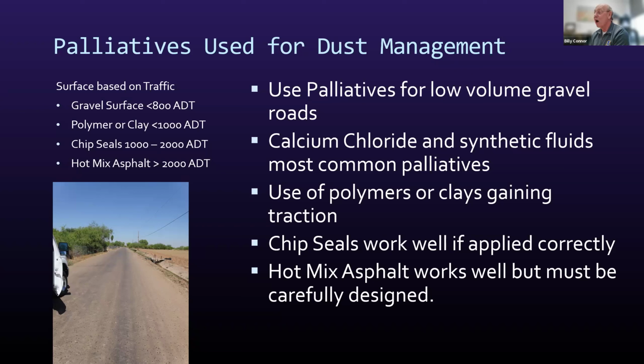Hot mix comes with a lot of equipment. You have your lay down equipment, all your rollers, your hot mix plant, and loaders to service the hot mix plant. So that makes it really expensive to use. The last number I got out in Nome was about $600 a ton. I think it's running around 200, 250 here in the interior. So it is quite expensive. And as I say, you want to make sure that you design it and that you hire experienced crews to put it down.